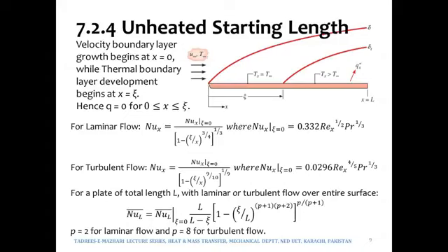For example, what I have seen various times is that students select the expression for Nusselt number wrongly. And how do they do that? They either assume or wrongly calculate that the flow is turbulent, and then they choose the wrong expression of Nusselt number. However, the flow was laminar, right?